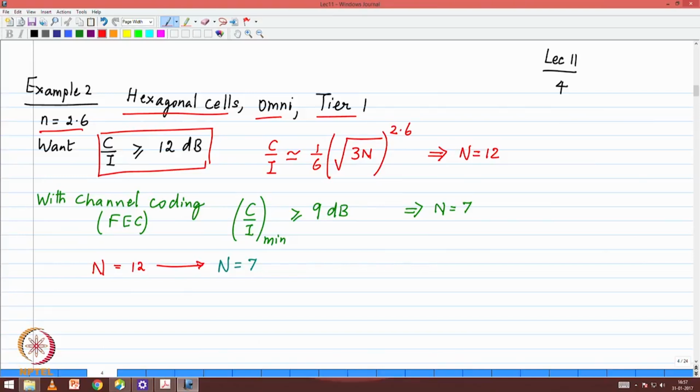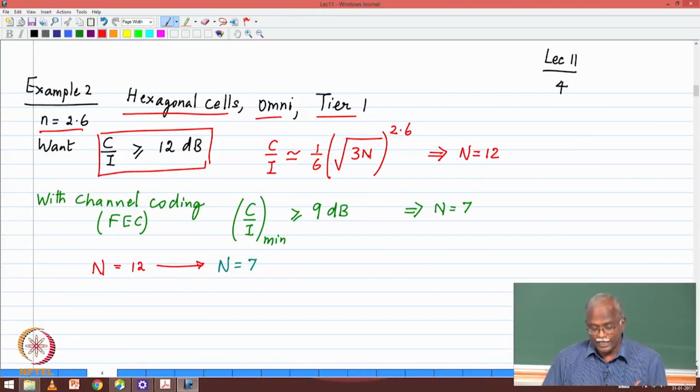Now, given that you're working in an environment where the channel will introduce a lot of errors, the introduction of error correcting codes, or forward error correction, or channel coding is very advantageous. So assume that you have introduced channel coding into your system, which means that you have to compress your source a little bit more. The little extra headroom that you have, you use it for error protection.